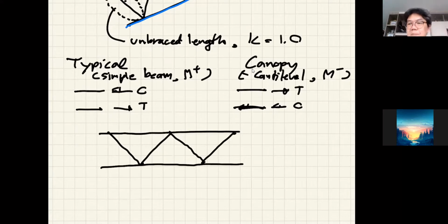When our top chord is under compression, let's say I have a member, maybe it's a tube, a pipe. If the buckling is going about this axis, it means that your member is going to dance up and down, correct? That means because of the presence of the joint, your member can only dance up and down, with the joint becoming the brace point.